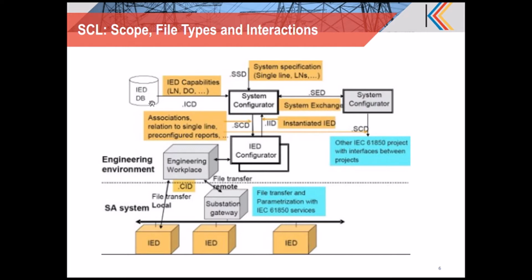The SSD file, along with the IED Capability Description, a published file of each IED known as an ICD file, is used for importing each IED onto the system and mapping it to the SSD elements. The actual data comes from these ICD files of the IEDs, and this is done by the system configuration tool. The output file generated is the Substation Configuration Description, an SCD file, which will be handed over to the corresponding IED configuration tools, which can be used to configure the specific vendor IEDs.